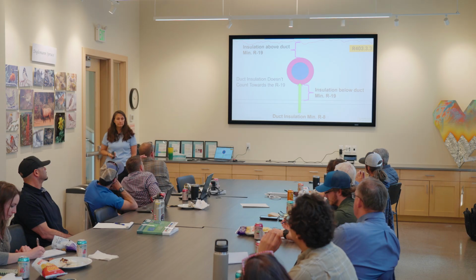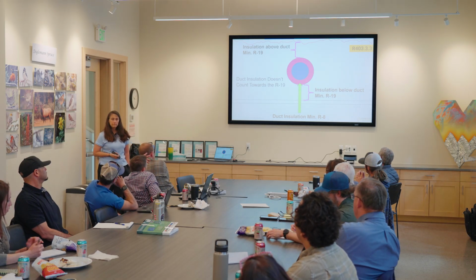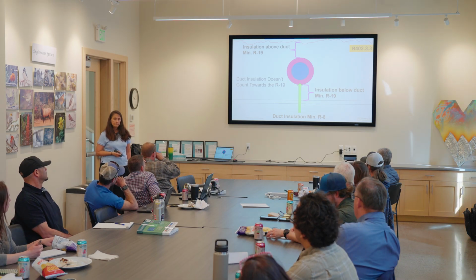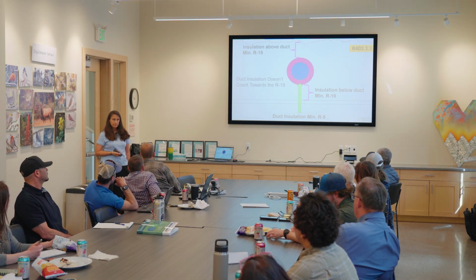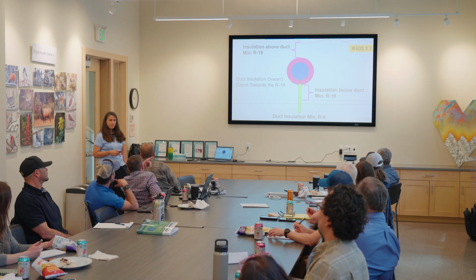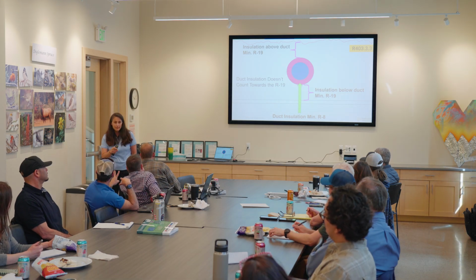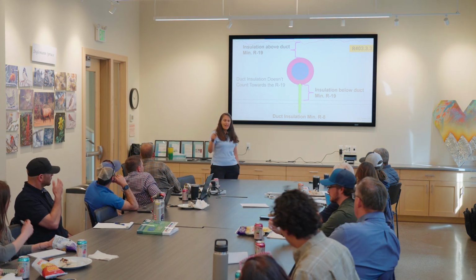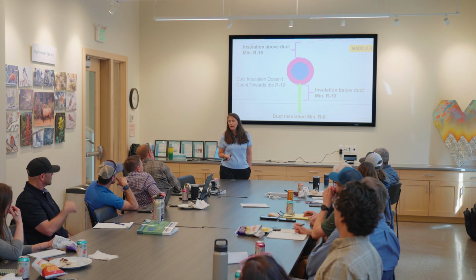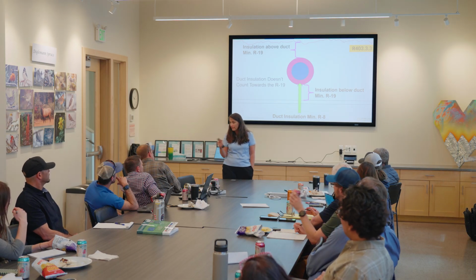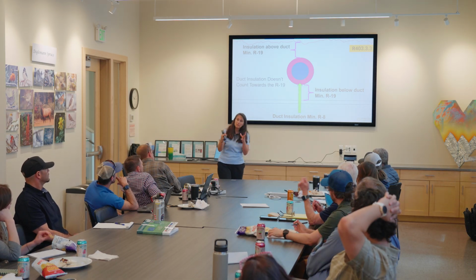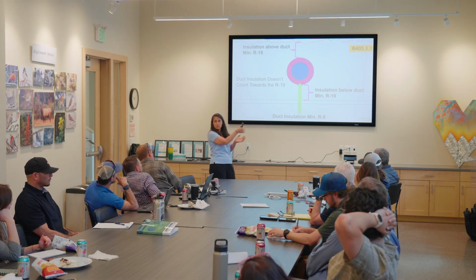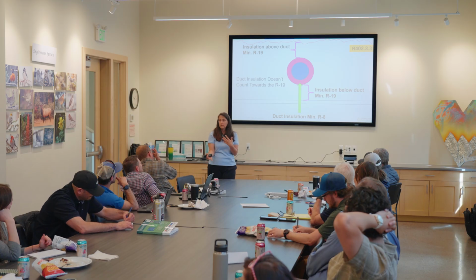My question is, if the duct is outside of the thermal envelope, then you just need R8. Correct. Why would anybody jump through the hoops to do this? Because if we go into R408, having your ductwork inside the thermal envelope isn't a bad way to go, and you might have a portion of your ductwork that you would have to comply with this to meet that other option in there.